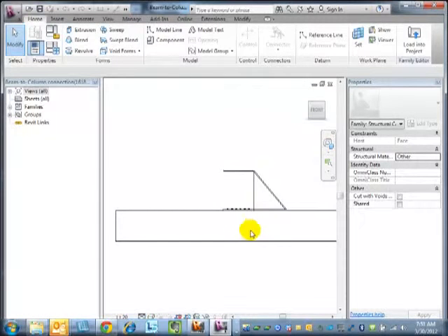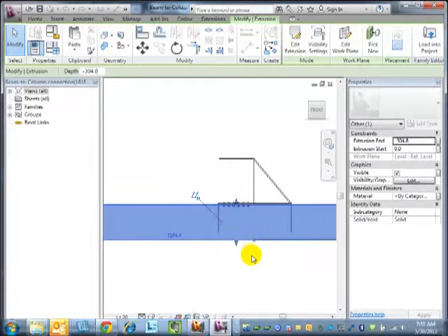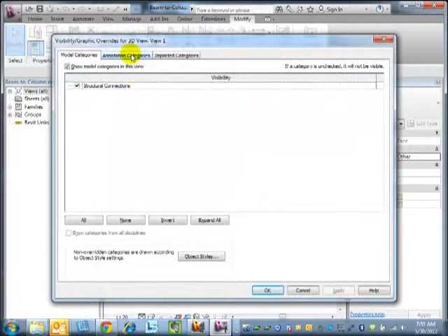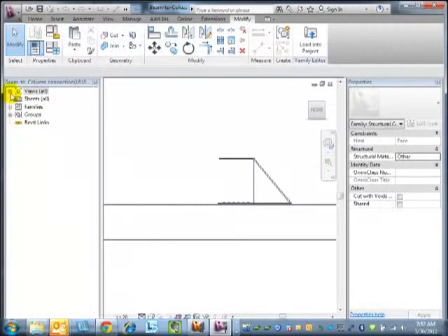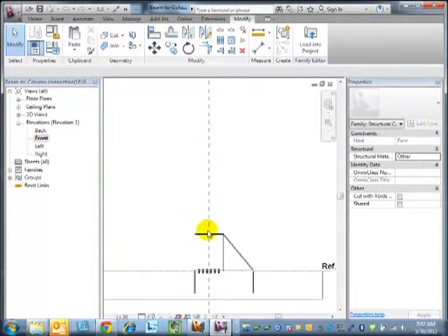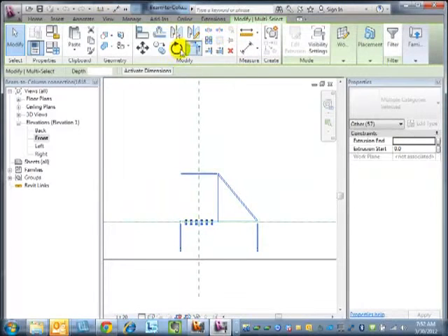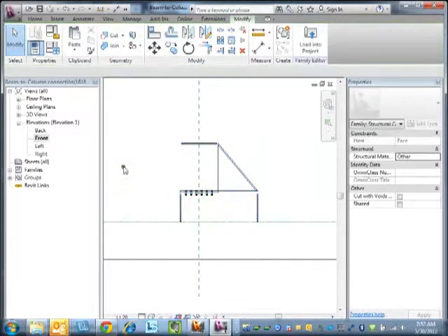And this being the element, which is the sort of placement face. Let me even turn on the dimensions. In this case, it's the column face. That's what it's using for that. Let me go ahead and do this thing, to try and understand a little bit. So that's the reference level. At this point, I think you can go ahead and redefine the family to say that you are now 2 feet off the face.